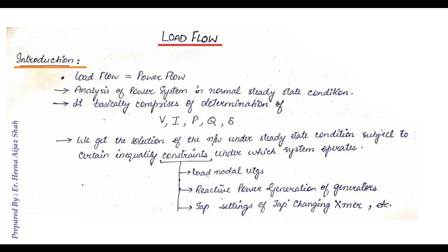Load flow is also known as power flow. By the term load flow analysis, we actually mean analyzing any power system in the normal steady state conditions. After analyzing any power system, we'll get the information about the four basic quantities, that is active power, reactive power, voltage and phase angle. So we get the solution of the network using the power flow analysis.